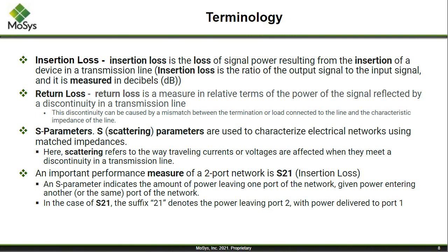But you also want to think about the design of a driver, in this case a SerDes driver. When they're specified, they're designed for a range of conditions under which you might place them. So insertion loss is not necessarily a bad thing. If you design a driver to drive, let's take the MoSys case we designed for, somewhere in the order of 10 inches of etch, so you might have 12 dB or something of etch that you can live with.